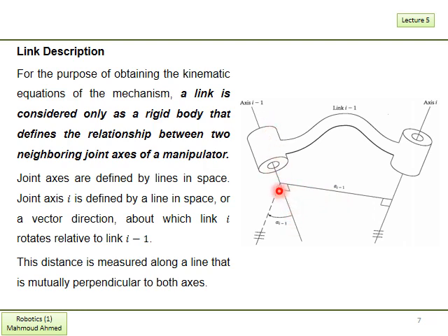We imagine we have a cylinder around this axis, and we simply increase the radius of the cylinder till the cylinder touches the axis I. At the point of tangency, at which the surface of the cylinder touches axis I, this radius is simply the perpendicular line a(I-1) between axis I-1 and axis I.